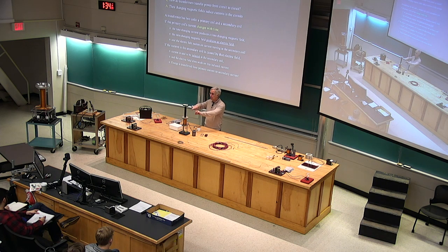So power, neutral is going to sit there at 0 volts. Power is going to go up to positive voltage, down to negative, up to positive, down to negative, back and forth. And current will therefore flow through the coil, which is wrapped this way. It'll flow first one way and then the other way, back and forth. And it reverses for 60 complete reversals per second, which means it's 120 individual reversals. Is that okay? So that's going to become magnetic.